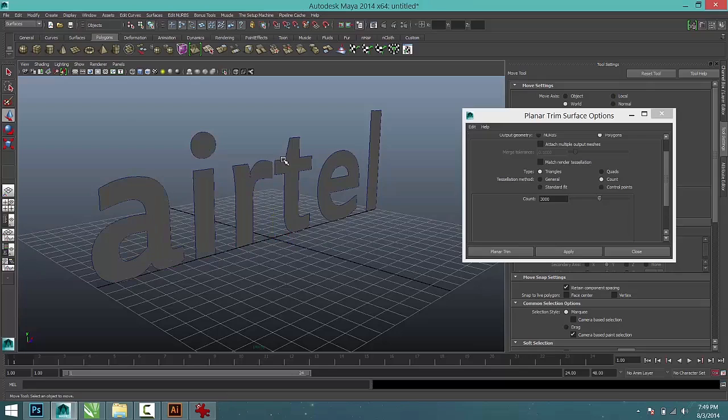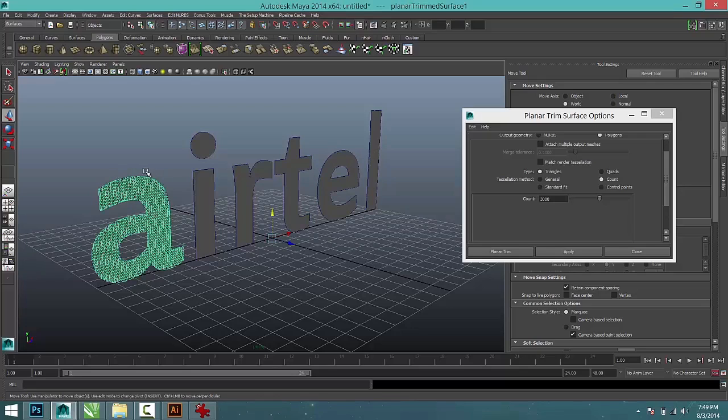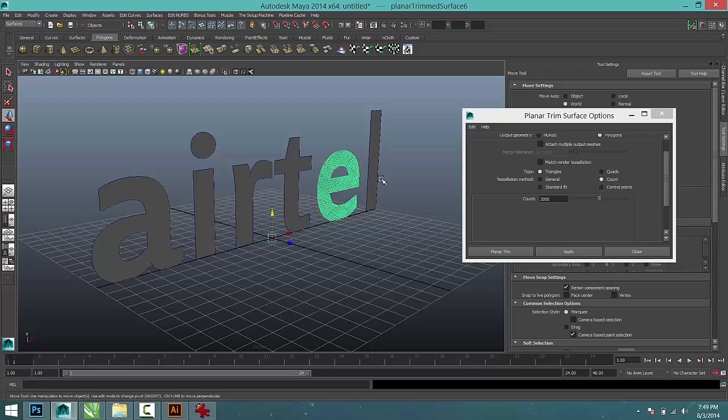Note that, as I said before, when you create objects from curves, the curves maintain an influence on the object, and so any change that you make to the curve usually registers again on the object. To do that, I explained that you need to delete the history from the new object you have created. So in a case like this where the curves are on the very same line in space that the surfaces are, how do I separate the curves?